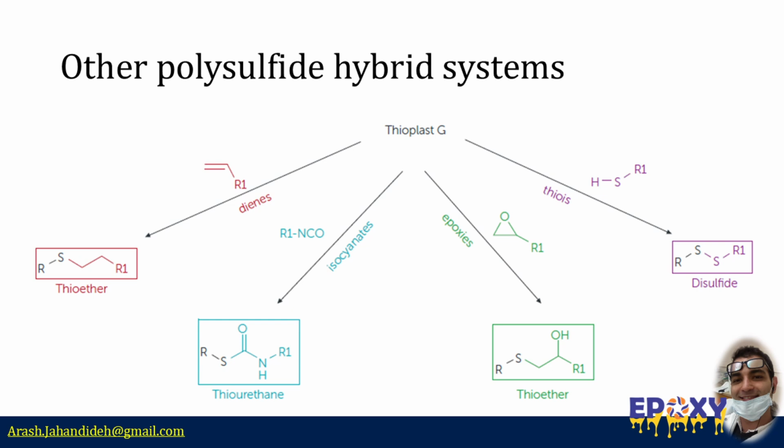Liquid polysulfides are highly versatile and can participate in controlled chemical reactions with a variety of other components, including diones, epoxies, triazones, vinyls, and allyl ethers, as well as phenolic resins. These reactions, carefully balanced in stoichiometric ratios, open up numerous commercial opportunities by tailoring material properties to specific applications.